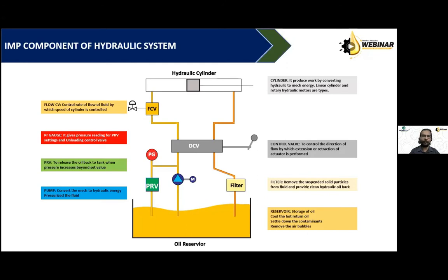They will keep on draining the oil even if system pressure is not above the requirement. Then flow control valves, these are mostly throttling valves. And whenever we are narrowing the passage for a liquid to flow, the liquid velocity will increase due to nozzle effect. And this high velocity mixed with any solid contaminant is the biggest culprit for a hydraulic system.